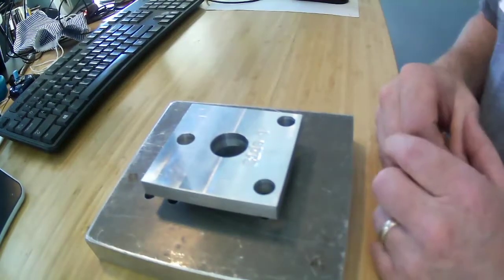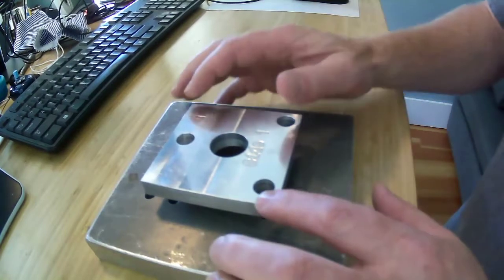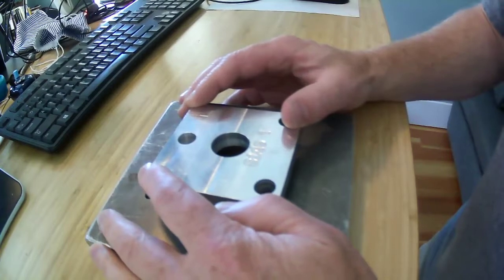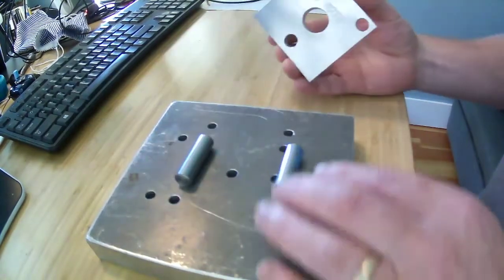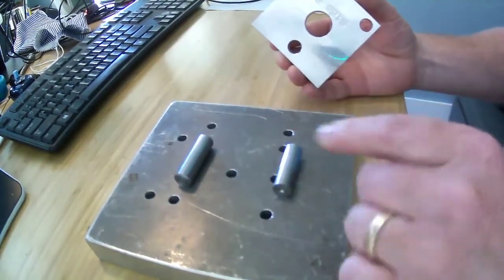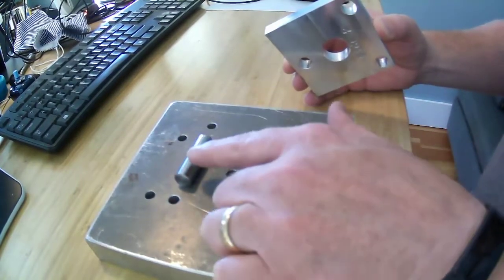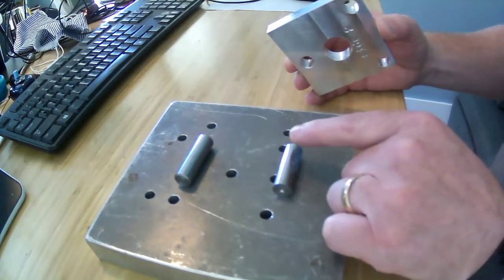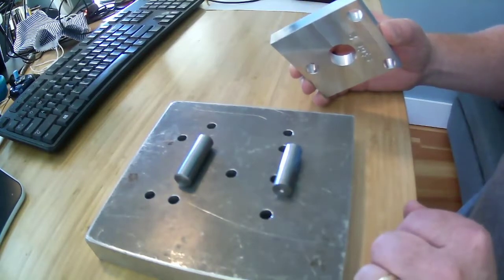I know a lot more about where it's contacting. But do I know where it's contacting? Not really. At some point, I think you can hear that. It is wobbling back and forth because it's still not deterministic. There are still two solutions. Either it's in contact with this entire dowel pin and one point on the front dowel pin, or it's in contact with the front dowel pin and only one point on the back dowel pin.